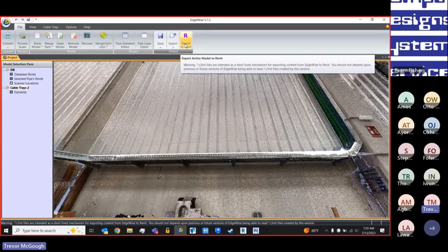So that way, whatever application you're modeling into, as you model your different systems, like piping, structural steel, whatever, as it comes into Plant 3D, AutoCAD, or Revit, it'll come in correctly aligned. And then at the end, you should be able to drop in your point cloud, and everything will be correctly aligned in your end application.